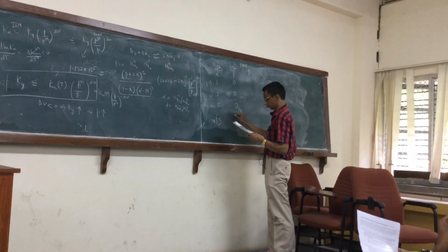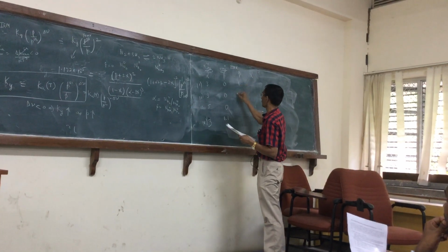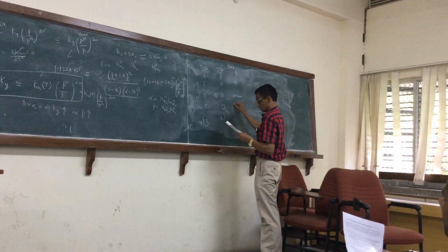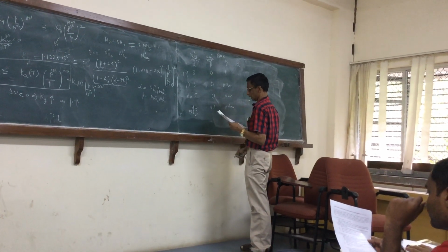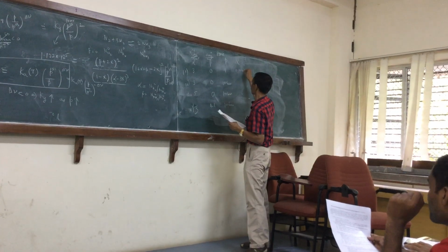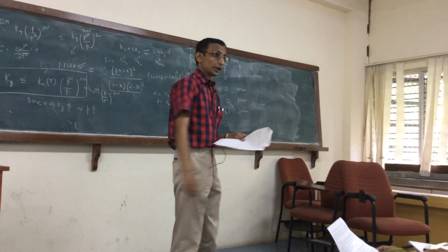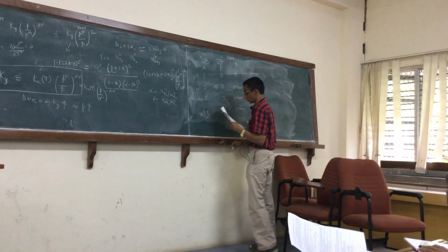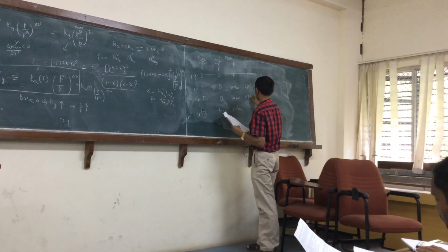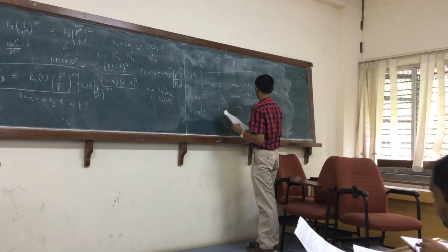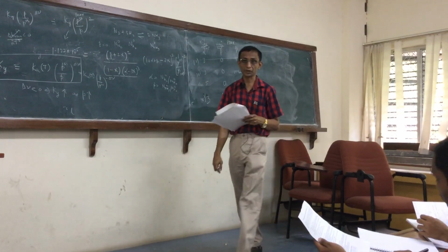Beta is 0, except for the last one, the beta is 0.1. The pressure is at 1 bar, 100 bar, again 100 bar, 100 bar. X we saw 0.002. So clearly this case is of very little value, very low equilibrium conversion. At 100 bar we saw it's around 0.165, 0.236, 0.124. From here to here, you can clearly see the effect of the pressure, quite dramatic.